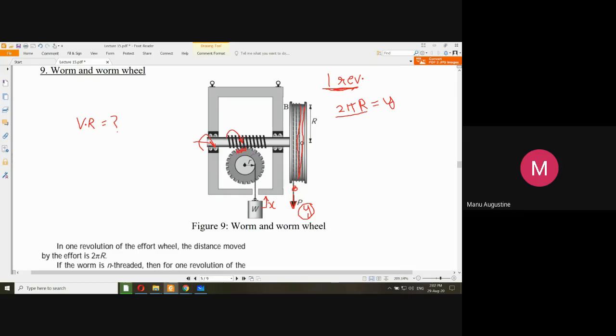In other words, when one complete rotation of this worm is enabled, only this much part of the total gear will rotate in this direction. Only this much rotation is possible, not one complete revolution. Only that part of a revolution which covers three teeth will be moved by the gear.